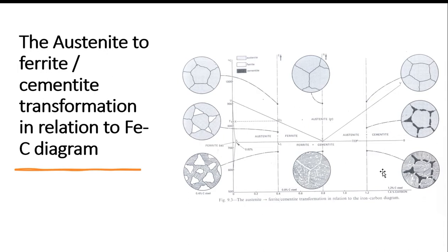Due to the forces applied on it, and again the friction, right? Then the vibrations and all that happening to the gear wheel, suddenly the temperature will increase. After increasing the temperature, the mechanical properties of that same part will change.